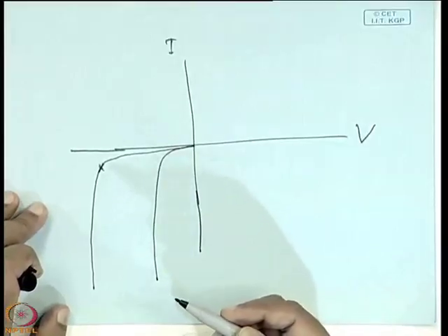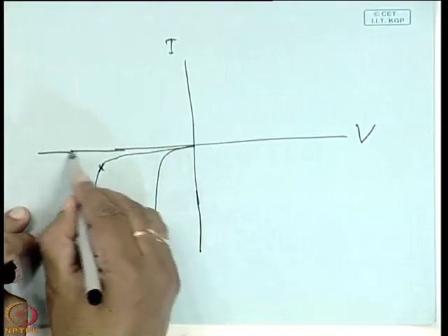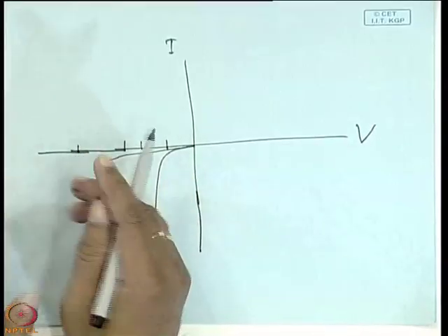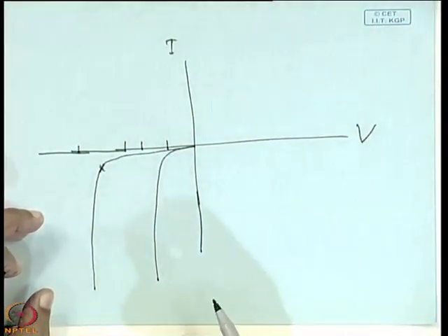What we want is that the breakdown occurs at a later stage, at very high voltage, say -1 volt, then -2 volt, -3 volt and so on, 10, 15, 50, 100, better if it becomes 220, your line voltage. That is a very important thing. If you use a silicon device, then the breakdown field is within minus 5 to 10 volt. But if it is a wide bandgap material, then its breakdown field is 50 to 60 volt.